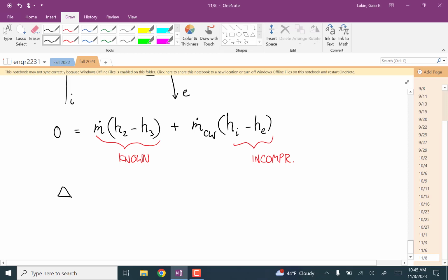Okay, so the change in specific enthalpy for the cooling water is equal to the change in specific internal energy plus the change in pressure times specific volume. The condenser, for the cooling water and for the working fluid, we're assuming that this is constant pressure. It's incompressible, so this whole thing goes away.